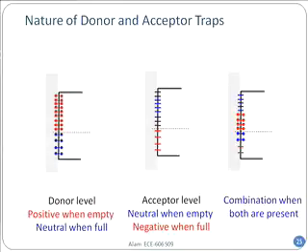These would be below the Fermi level. That means those will be negatively charged, because these are acceptors. When they have an extra electron, then they are negatively charged. And so from here, depending on the Fermi level, you can see I can tune how many positive and negative charges I have on the surface, right? And that will give me different amounts of threshold voltage shift. So that's what I'm after.